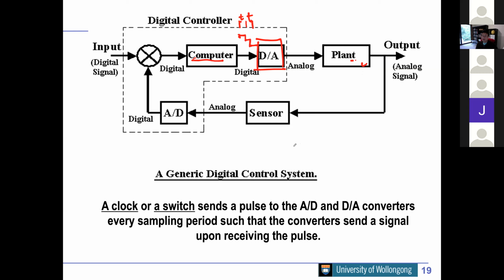Going back, the signal that goes to the computer is only those dots. The sensor is measuring a continuous signal, then we do what is called sampling, or analog to digital conversion. You take some values out of this measurement, which is also your sampling time.